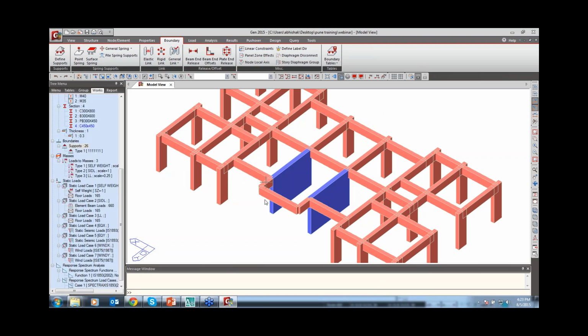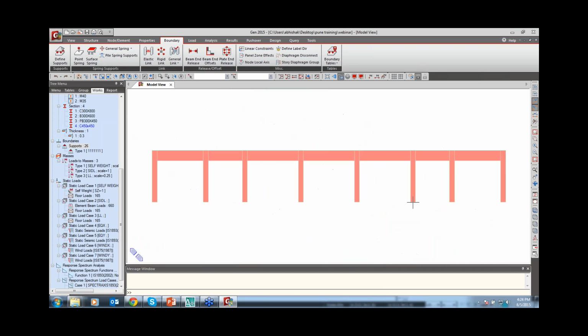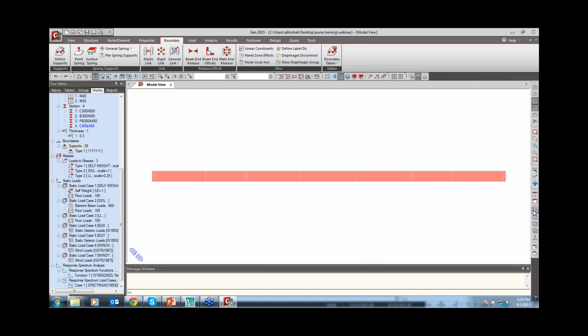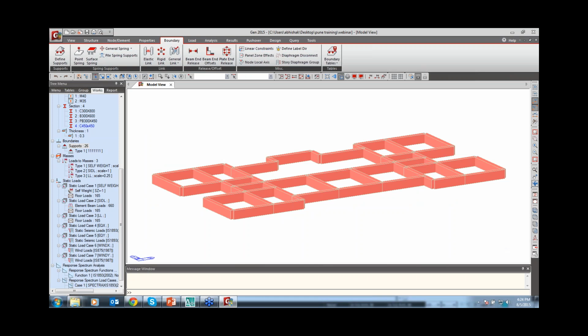So only that connecting member is required. Right now I have shown you how to generate it in between the panels. Now the next question is asked by Pramod Berry: how to insert the sub members, that is the secondary beams. Yeah, so for the sub members we have a good option. Generally, first of all you have to generate some nodes.